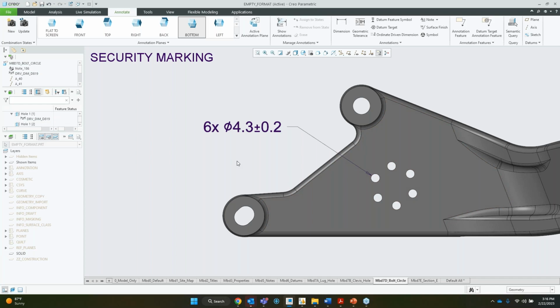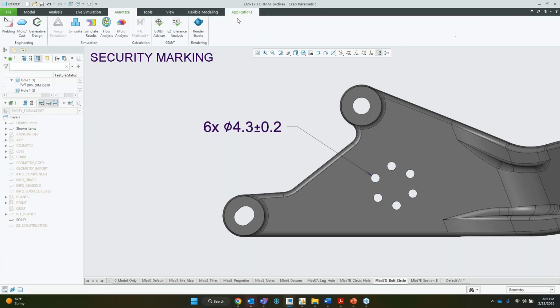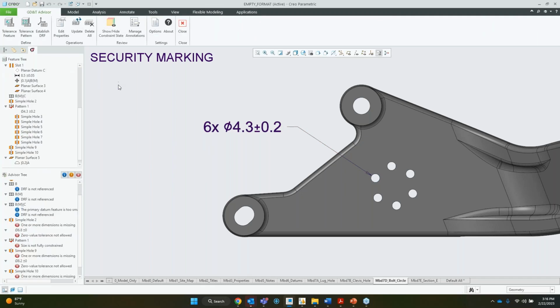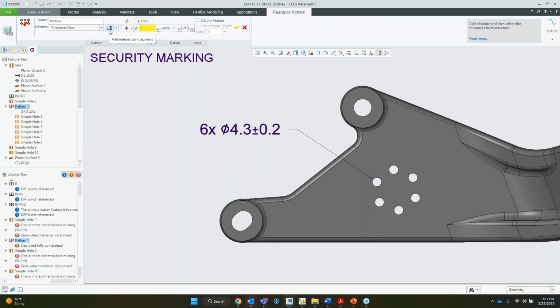Now what I need here as well is my tolerances. I've not changed my tolerances here. I'll just keep it at 0.2. I'm fine with this tolerance here. Let's go ahead and add some GD&T information, tolerance information here. So let's say this is the pattern which I want to add to, and I'll right click on this and say edit. So I'll add one of these, right?